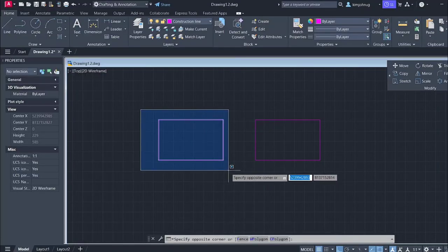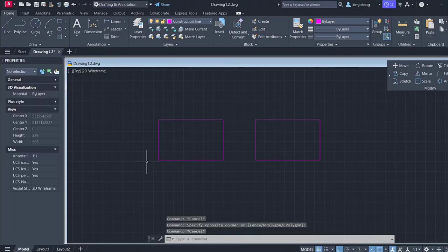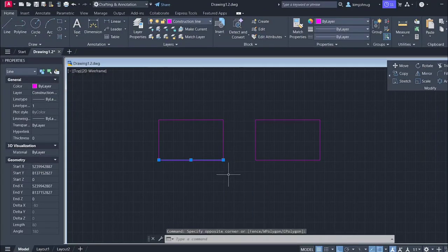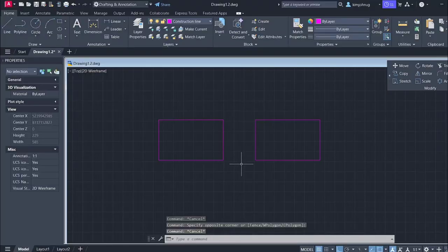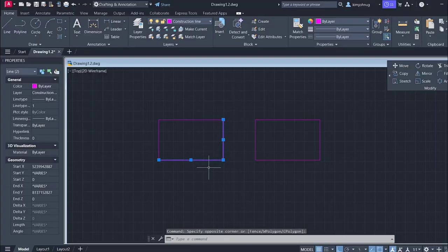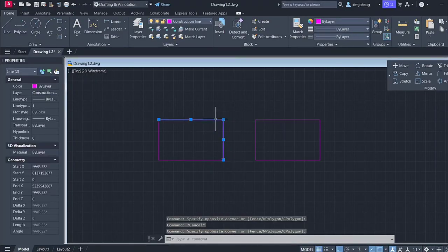So if I stop here, it will only select this line which is complete. So if I do the same thing down, it won't select it until I complete the selection to the end point of the line. But if I use right to left, we're seeing how it simply selects the lines immediately by just touching the corners.